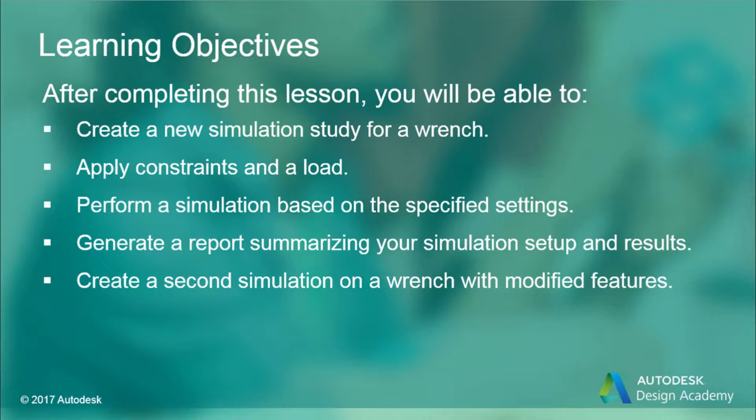After completing this lesson, you will be able to create a new simulation study for a wrench, apply constraints and a load, perform a simulation based on the specified settings, generate a report summarizing your simulation setup and results, and create a second simulation on a wrench with modified features.